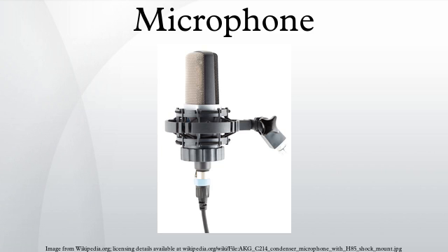Often MEMS microphones have built-in analog-to-digital converter circuits on the same CMOS chip, making the chip a digital microphone and so more readily integrated with modern digital products. Major manufacturers producing MEMS silicon microphones are Wolfson Microelectronics, Analog Devices, Akustica, Infineon, Knowles Electronics, Memstech, NXP Semiconductors, Sony, AAC Acoustic Technologies, and Omron.